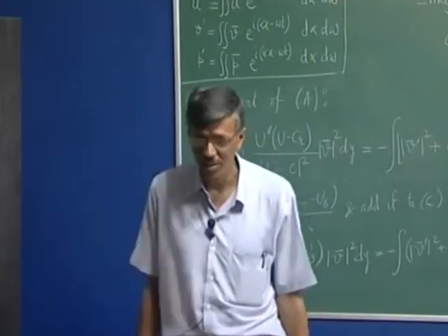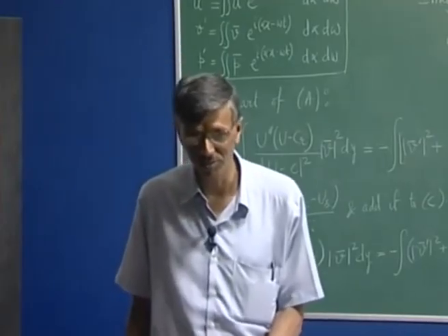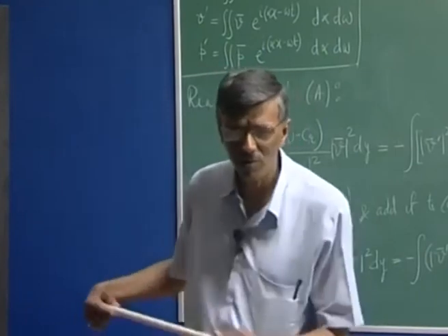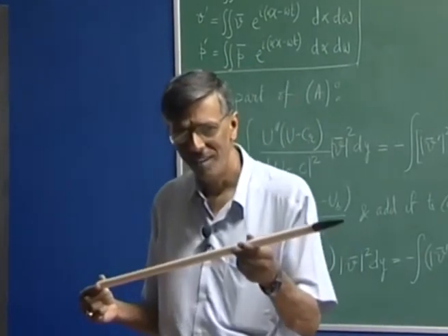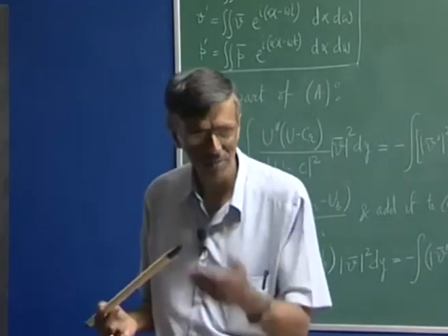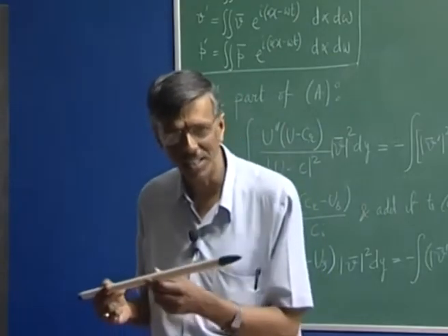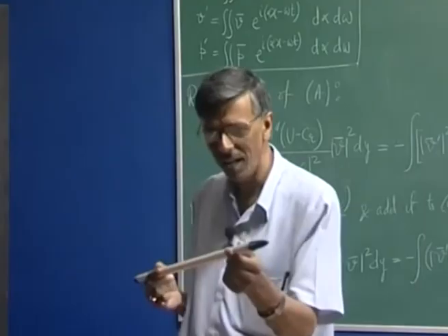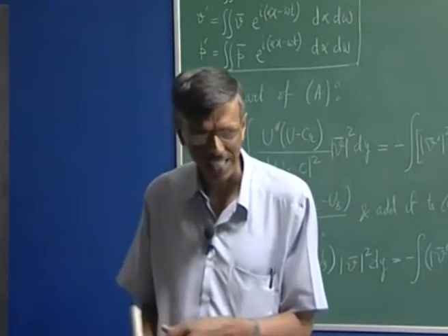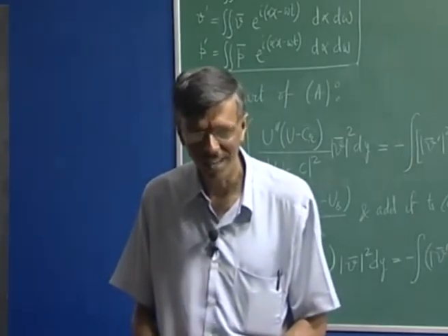Now, please understand streamline is a concept of 2-dimensional flows, but that again depends on our point of view. If I go along the direction of the flow, I can once again define the flow as 2-dimensional. So, again I can consider the streamline along the flow direction and view it as a vector, and that is what is called the vector potential, right.